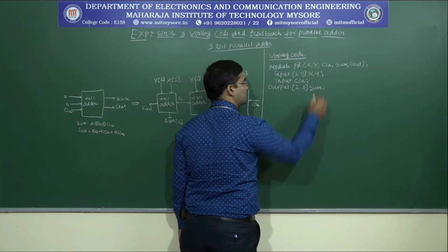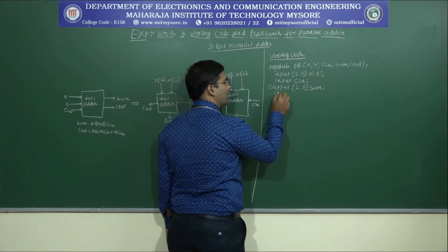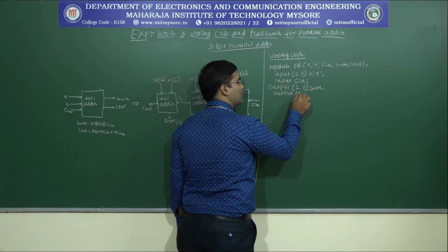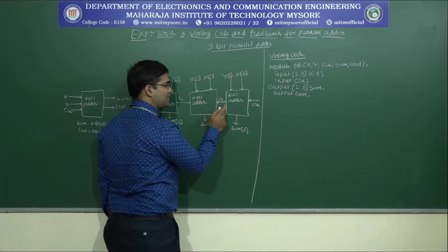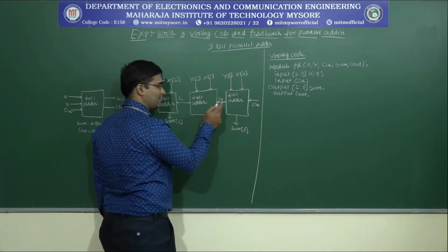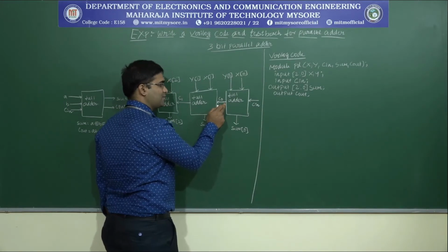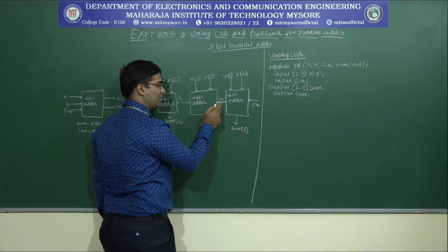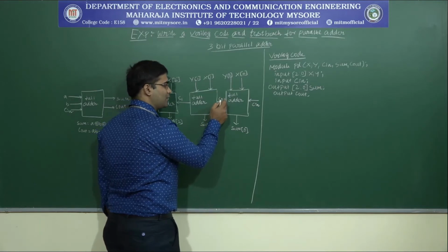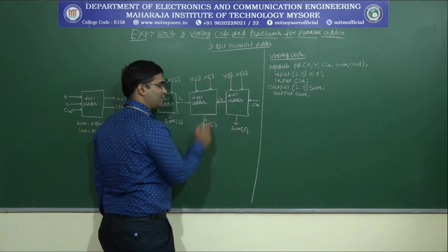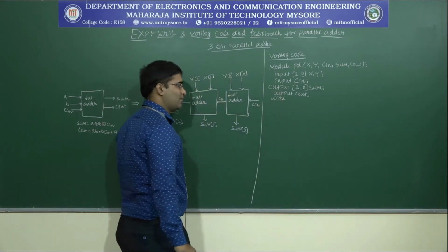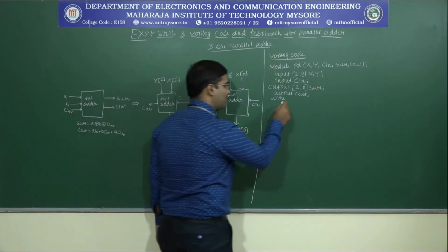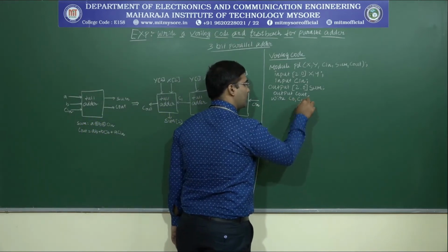we do have the output as again a 3-bit representation, which is sum, and we do have the output which is Cout, and there is a connection between the first full adder to the second full adder, that is specifically the output of the first full adder is connected to the input of the second full adder, and the signal is moving from the output of the first to the second full adder, and we are defining with a predefined word which is called wire, C0 and C1.